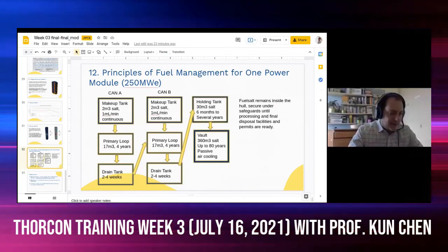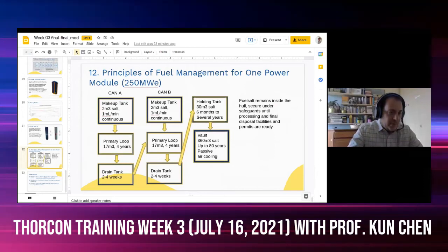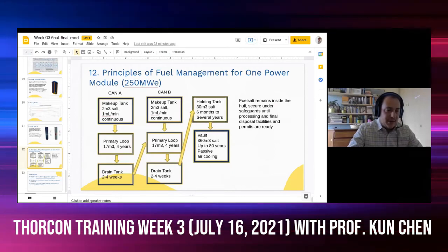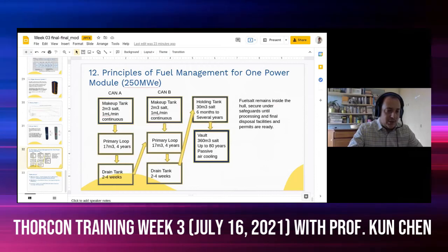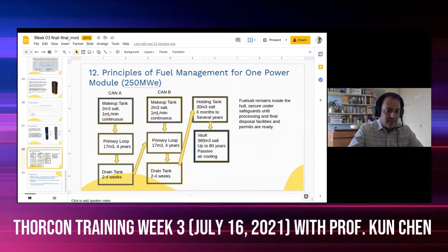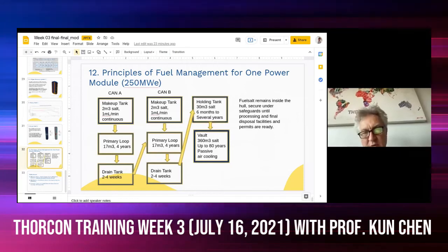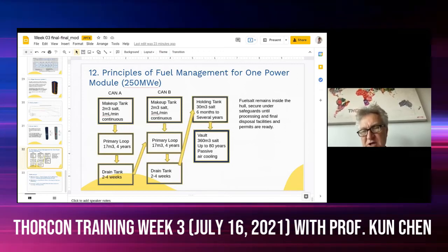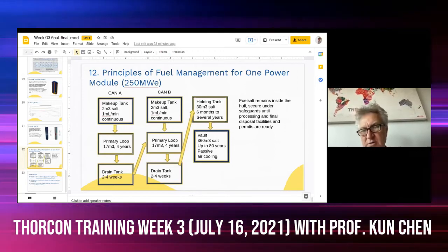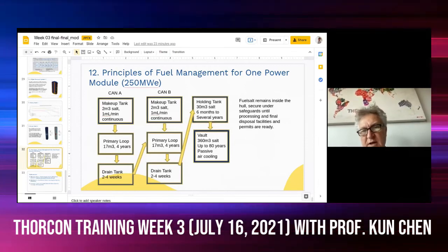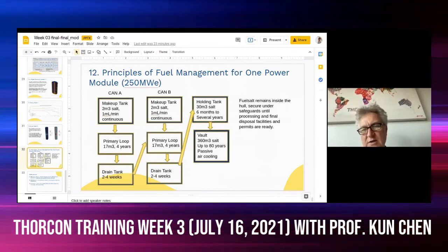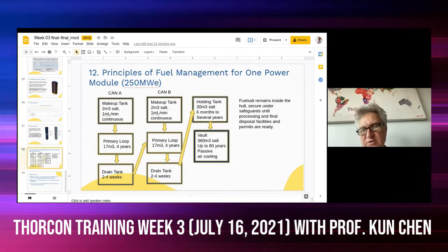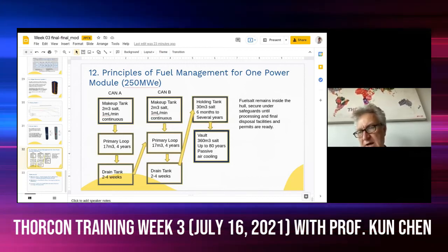I guess related is the latest question, question 3. The opening process of the freeze valve is passive. What is active is keeping the valve closed and the salt solid. The freeze valve, the center part of it, is kept cold with helium that's actively pumped. The salt adjacent to it is kept hot with electrical heaters. So if you lose the electrical heaters, if the temperatures are not in the right range, or you lose electricity, then the thermal capacitance of the salt adjacent to the frozen section will melt it completely passively.